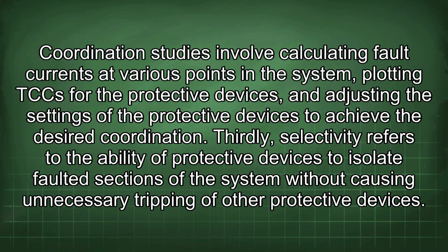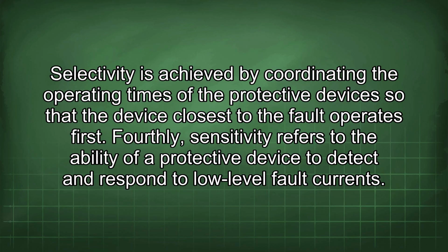Thirdly, selectivity refers to the ability of protective devices to isolate faulted sections of the system without causing unnecessary tripping of other protective devices. Selectivity is achieved by coordinating the operating times of the protective devices so that the device closest to the fault operates first.